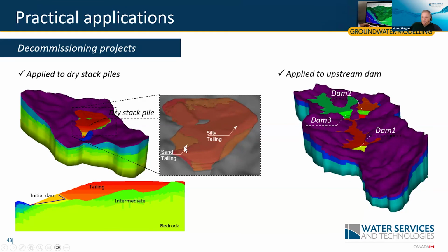In this case, sometimes it's very important that you end up knowing the heterogeneity within the tailings itself, because that may play a big role if we have tested a case where you have a homogeneous material assumption or heterogeneous, and it may cause some big surprise if you don't take the heterogeneities into account. You have to be able to represent very well the drainage structures within the dams itself. So you should use a model like FEFLOW or any structural grid MODFLOW to be able to represent things not only vertical in a stair-shaped case, but actually as close as possible to your property here.